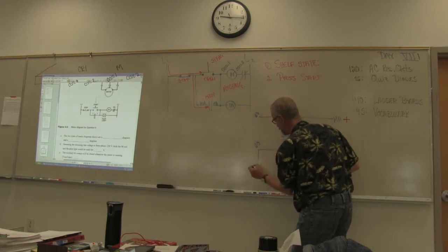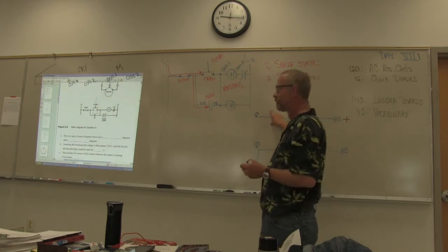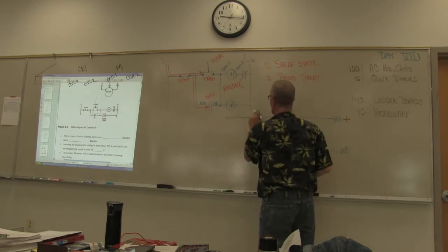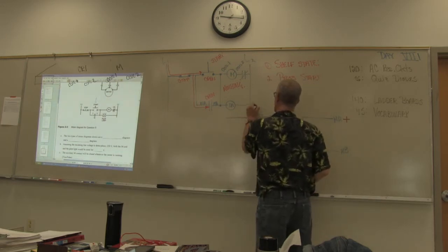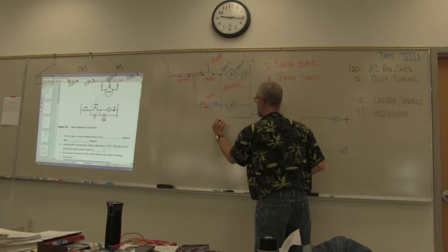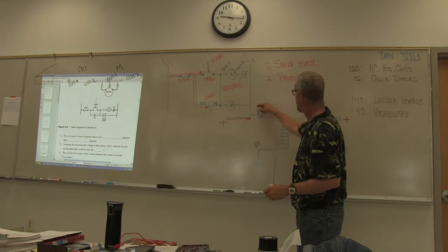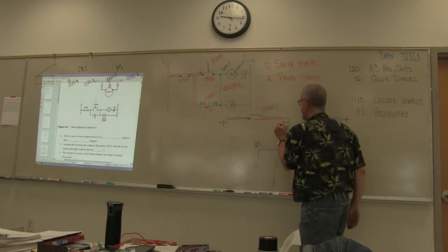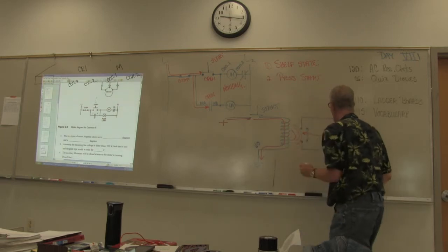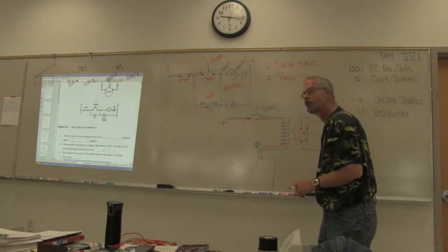Okay, let's consider this to be our neutral or ground, okay? What do I need to turn on that coil? I need to have a plus, power, to turn on that coil. So here's my start switch. And here's my plus sign. Okay, energy is going right to there. As soon as I press that start, energy flows through here, creates a magnetic field, which pulls this closed and allows this to do its thing. I hope you caught that.